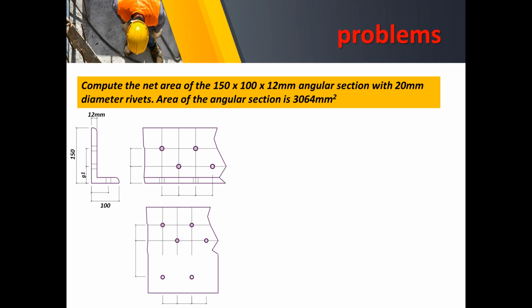So, just like what was introduced last time about the calculation of the gauge distance, all we need is to label or get the distance of your bolt to the nearest corner, and say that is G1, okay? So in this case, that is 56.25. Likewise, for the other element, you get the distance from the corner up to the center of your bolt or nearest connection, say G2. Okay? In this case, we have 62.5.